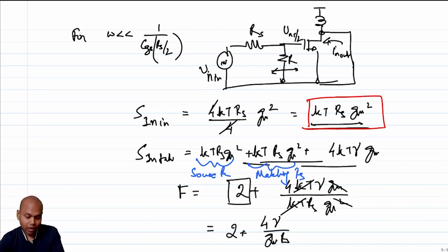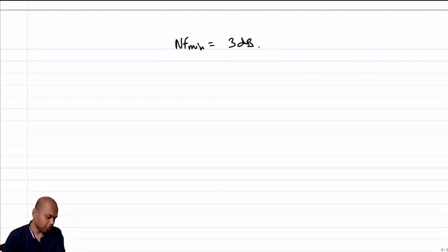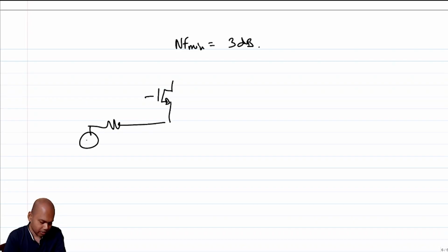Now you might say, why common source amplifier? Why not a common gate amplifier? We understand the common gate amplifier also is a way of matching. Sure, but I will not prove this to you, I will just submit that even if you have a common gate amplifier with R_S, and let's say the input impedance, that is 1 over g_m, is equal to R_S, you design it in such a way that this is true.